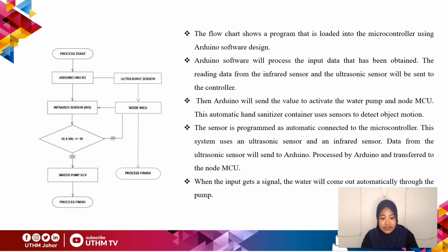This automatic hand sanitizer container uses sensors to detect object motion. The sensor is programmed as automatic, connected to the microcontroller. This system uses an ultrasonic sensor and an infrared sensor. Data from the ultrasonic sensor will be sent to the Arduino, processed by the Arduino and transferred to the NodeMCU. When the input gets a signal, the water will come out automatically through the pump.